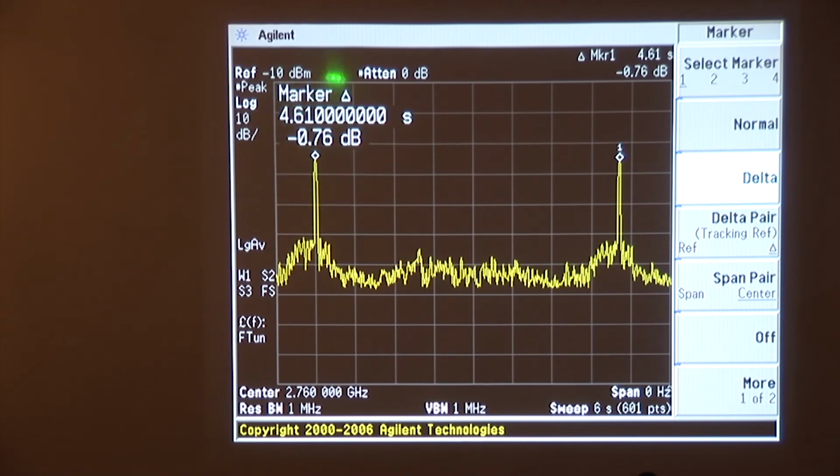This is a way of identifying radars. Even if a set of radars are all of the same model number, they'll typically vary ever so slightly in their actual rotation time, so 4.61 seconds. We note that, and at this point we would also record this scan, because this scan shows us the antenna radiation pattern at the location of our measurement system. We're not getting a lot of dynamic range on that 30 miles from the radar, but we are seeing some of those side lobe structures in the radar pattern here.